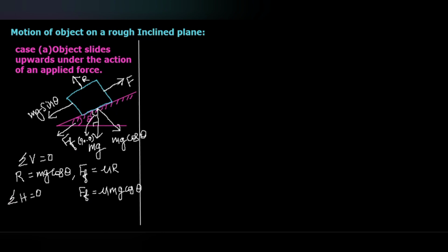under the action of the applied force F, if this object moves upward. Okay, that means if this is the direction of motion, then the inertia force ma will act opposite to the direction of motion. Okay, so for the horizontal force, that also we have to consider.